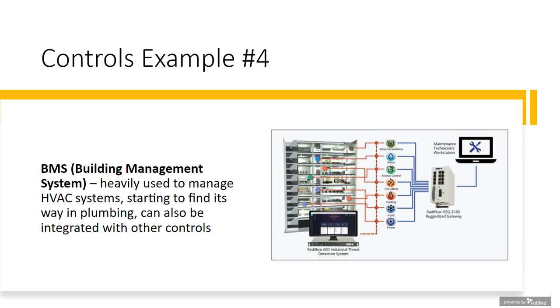So one of the things to keep in mind as we go through these examples, and you're charged with the challenge of basically doing some type of an automation process for thermal disinfection, I would recommend first you talk to the controls people on the project to see if there is a building management system in place or that will be in place, because what you may want to do is piggyback off of this building management system to do your thermal disinfection.